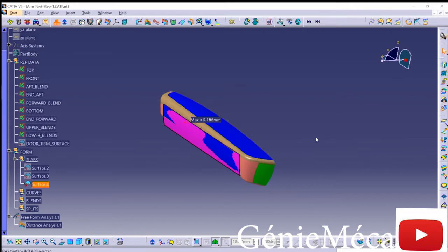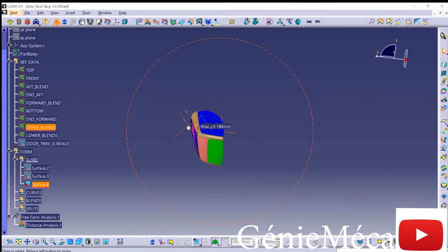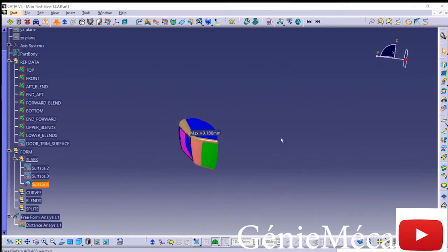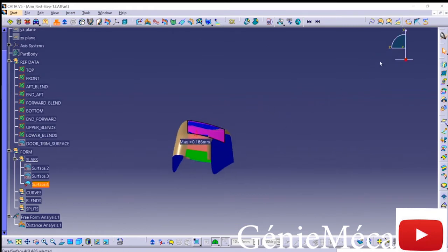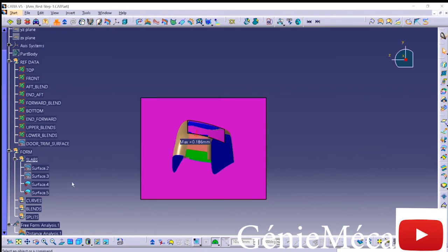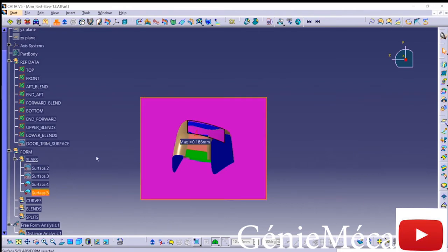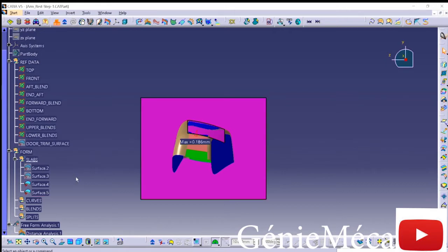Now I want to do the ends. So once again, I want to sight down, click on my X, right mouse click. This is my YZ plane, and draw in my planar patch. Since I'm going to use two of these, I'm going to take this and I'm going to Control C on the keyboard for copy and Control V on the keyboard to paste. So now I have those two.